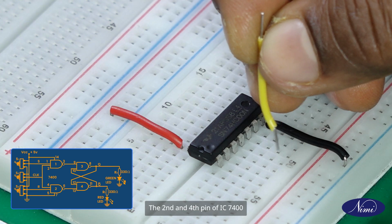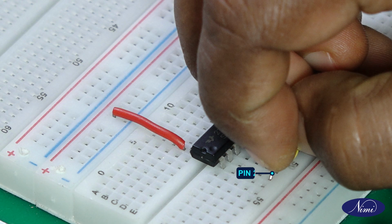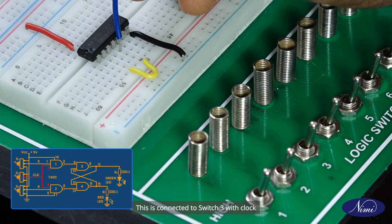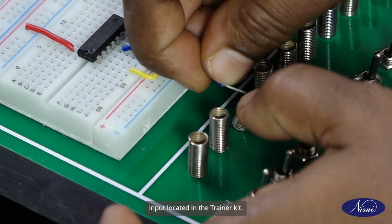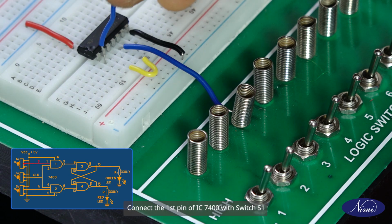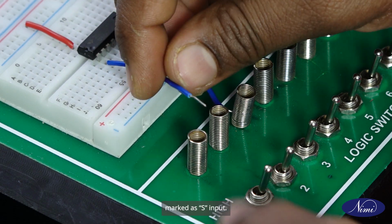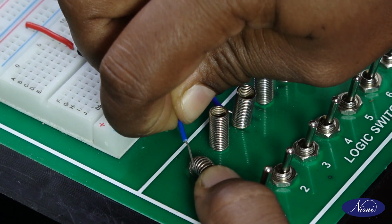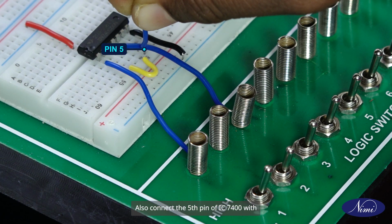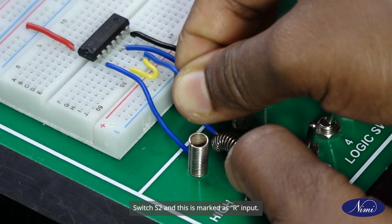The 2nd and 4th pin of IC 7400 are coupled together. This is connected to switch 3 with clock input located in the trainer kit. Connect the first pin of IC 7400 with switch S1 located in the trainer kit, and this is marked as S input. Also, connect the 5th pin of IC 7400 with switch S2, and this is marked as R input.